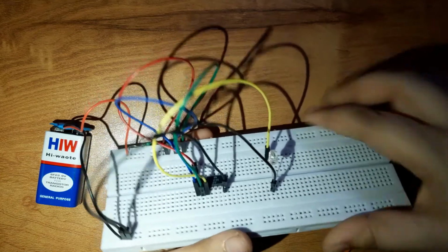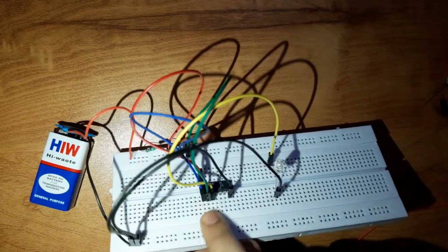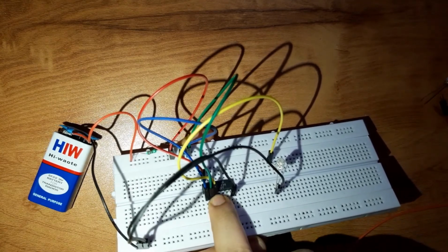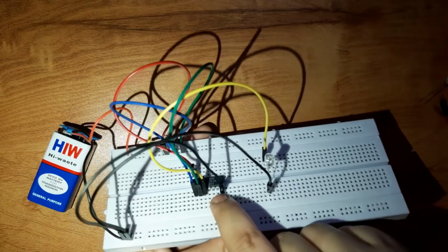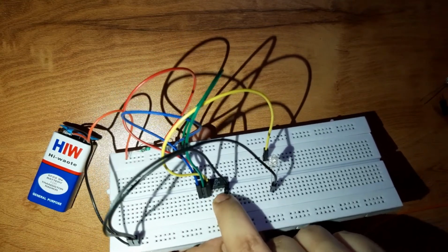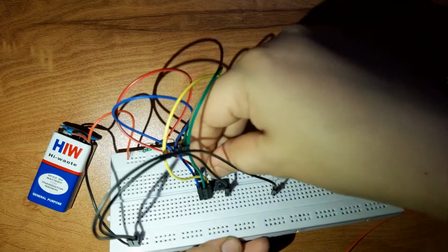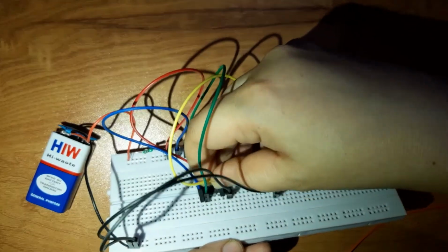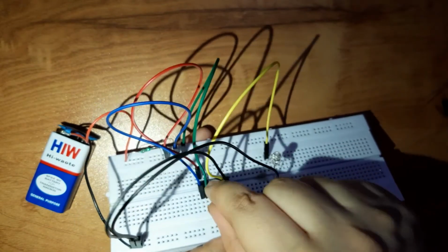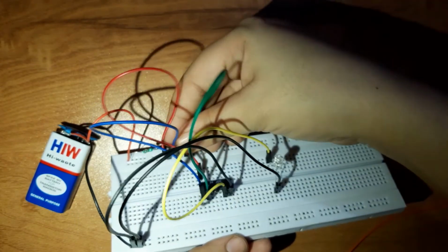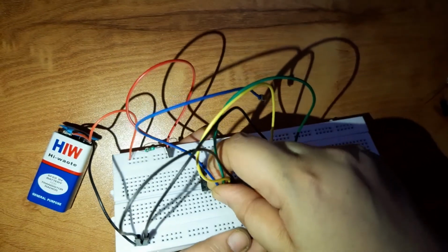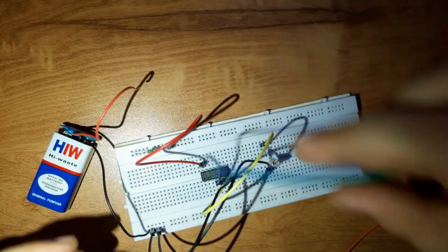So this is the truth table verification for the NAND gate. Now I was using the first 3 pins, wherein the first 2 pins were inputs and the third pin was the output. Now I will be using the remaining group of pins, that is the 4th pin and 5th pin as inputs and the 6th pin as output. So I'm simply exchanging this wire. The 6th pin is the output, and now I'm connecting these two input pins to the 4th and 5th.